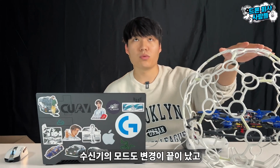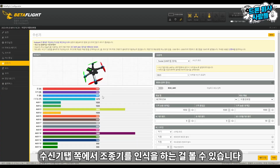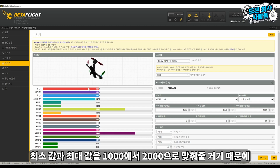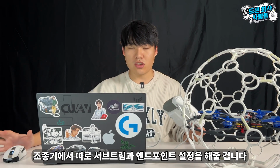Now that the receiver's mode has been changed and the controller is set to S-bus mode, you can see the controller being recognized in the receiver tab. The neutral value for the tricopter is set to 1500 and the minimum and maximum values are set from 1000 to 2000. So we will separately adjust the sub-trim and endpoints on the controller.